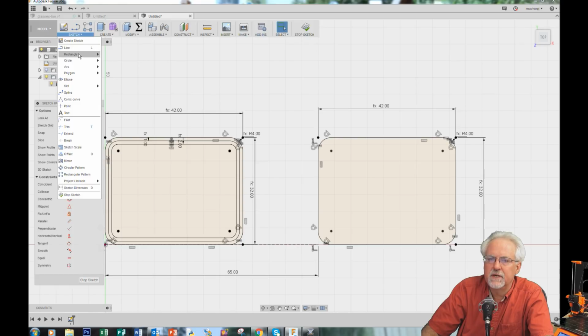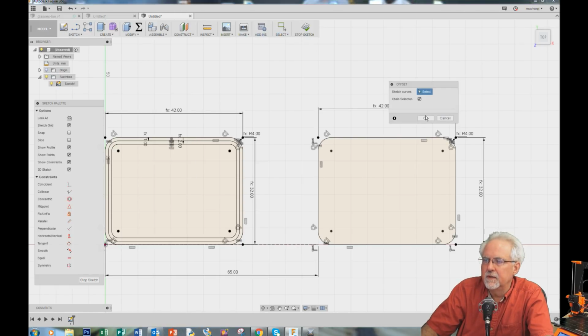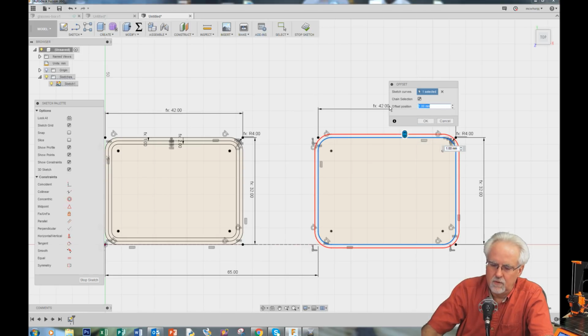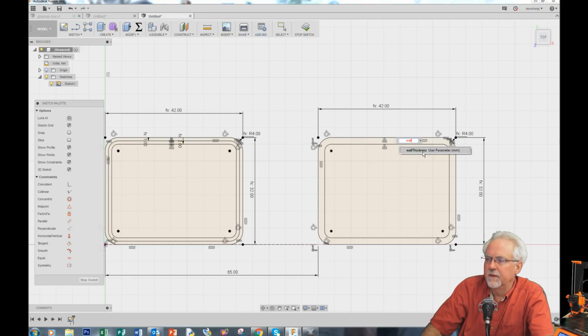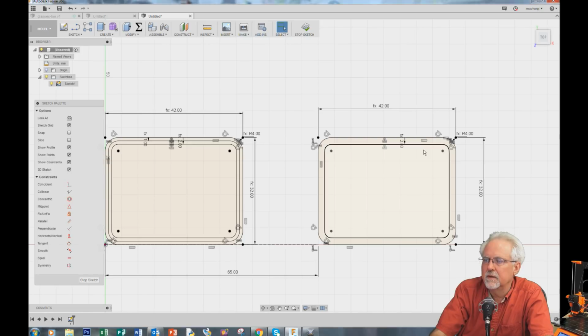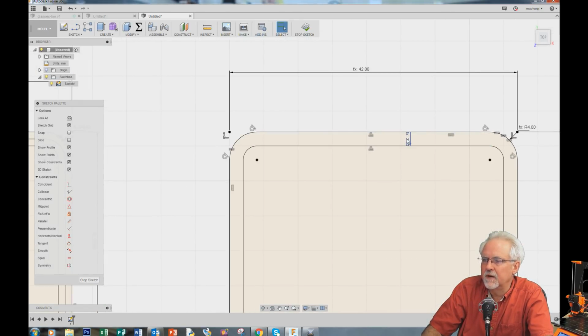Okay, what do we do now? We have two offsets. We come in and we do offset. I want to go from here. And what do I want? I want a minus wall thickness, enter. Okay, what did it do? Messed up again. So we put, this time, wall thickness, enter. Okay, what do I have? I've got wall thickness correct now as a variable.